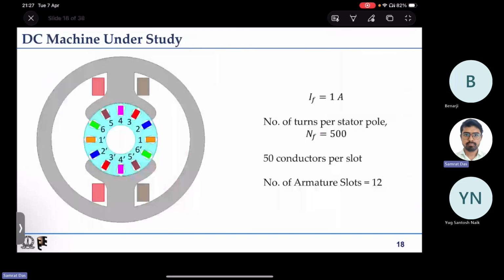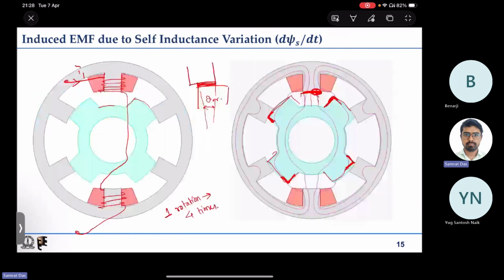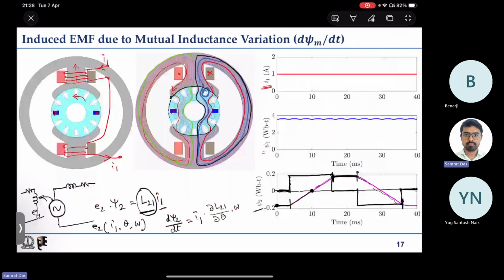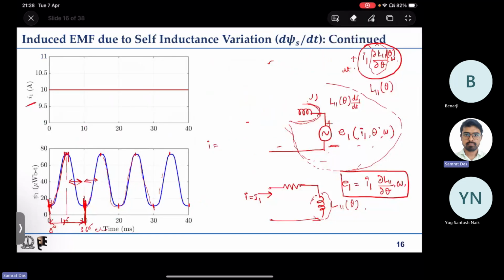Okay, probably. So earlier we have been discussing the flux density distribution along the air gap. Using the integral of H dot dl, like that you can get the B distribution along the air gap. So B is almost constant under one pole, then falls from the positive value to 0 in the interpolar region, and again it is B under another pole. I don't think I have that in this slide, but I can probably erase this one.